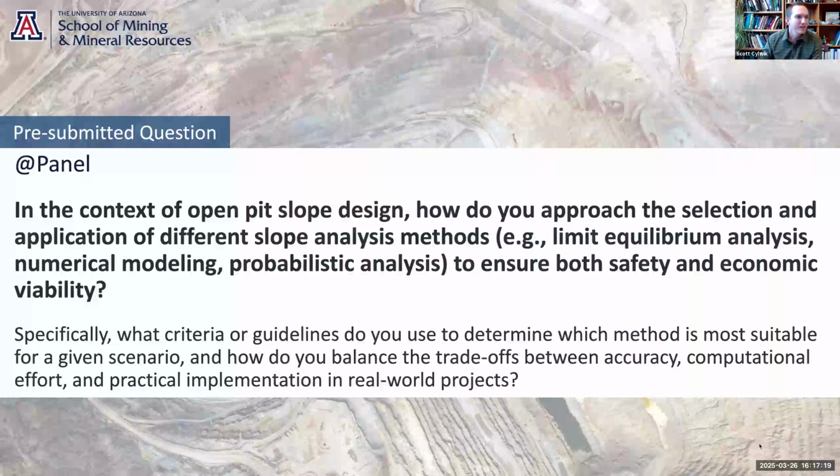One keyword I haven't heard yet is the geology model. When I think, how do you approach the selection of slope analysis method? It's like, okay, well, definitely want to take a good hard look at the geology model. What's the geology doing? What's the structure doing? How does that interact with the pit design that's been proposed? Just from that, you should be able to conceptualize what types of failure mechanisms we could have. And then you want to make sure you pick a tool that can analyze that failure mechanism properly, because not every tool can analyze every different failure mechanism.